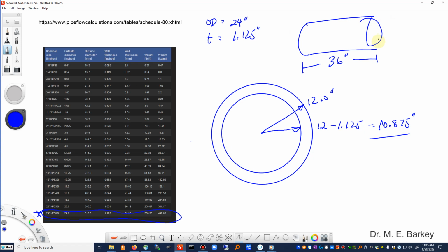We're going to apply a simple tension load on it. We're going to over constrain one edge, and we're going to see why that's probably something we don't want to do. We're going to relax the constraints and set up a local coordinate system in Abaqus so that we do R and theta constraints. We're going to do Z and theta constraints. We're going to allow it to freely expand or contract in the R direction, and we're going to see that we get a much cleaner, uniform stress distribution.